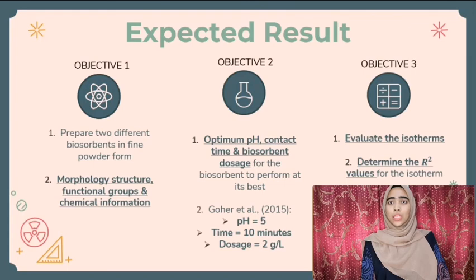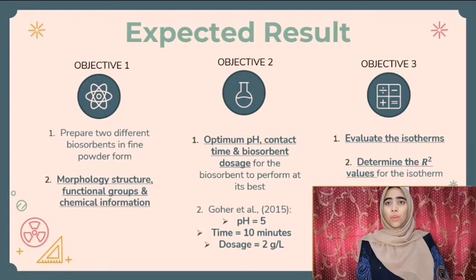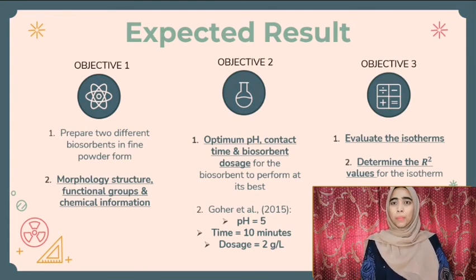The last objective is to determine the best isotherm to be used in this study. 2 mathematical methods will be studied, the Langmuir and Freundlich adsorption isotherms. The adsorption isotherm indicates the behavior of adsorbent interaction, which helps in designing an appropriate adsorption process. Plotted graphs for both isotherms will determine which model has the best fit linear line with the nearest R-square value to 1.0. At the end of this evaluation, Langmuir is expected to be the best isotherm to be used.